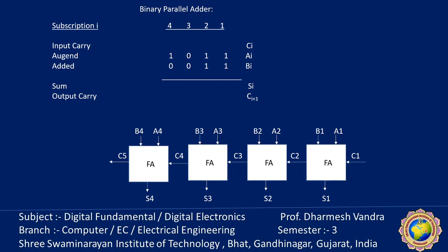As I already said, the input carry C4 does not settle to its final value, and C4 being stable depends on C3. C3 depends on C2 and C2 depends on C1. So C3 has to wait for C2, and so on down to C1. Thus, only after the carry has propagated through all stages do the last outputs S4 and C5 settle to their final steady state.